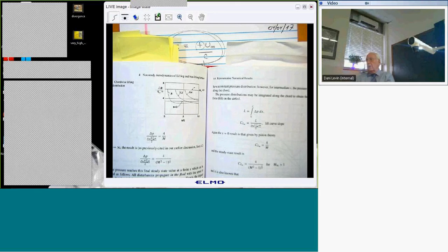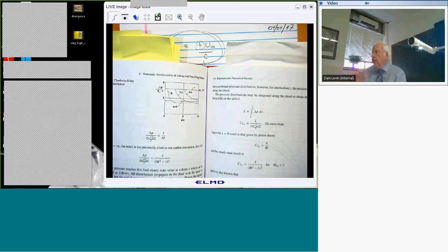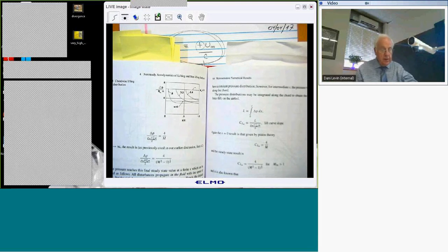So if I compute the non-dimensional time it takes, well, the physical time is the chord length divided by the propagation speed, which is U infinity minus a infinity. Even if I non-dimensionalize that, I find that when the non-dimensional time s is greater than 2 over the Mach number minus 1, nothing more is going to change, unless I keep moving the airfoil. But if I just move it once and hold it, in finite time, all those disturbances will propagate in the wing fixed coordinate system off the airfoil. And nothing after that will change. Okay? And how do you see that? Well, I'm glad you asked.